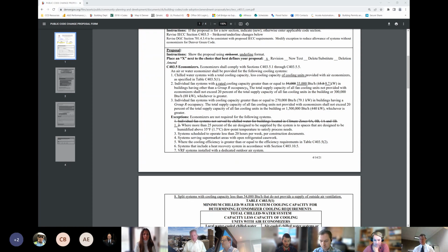Now, for what maybe people are thinking about when the words and letters VRF are put next to each other, is a heat recovery VRF system. The pretty color brochure of a heat recovery system shows some units painted red, some units painted blue, implying they can swap heat all day long, and therefore harvesting the interior heat, distributing it to the exterior, and therefore that's usually the justification for not needing an economizer.